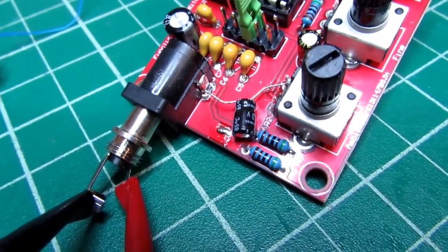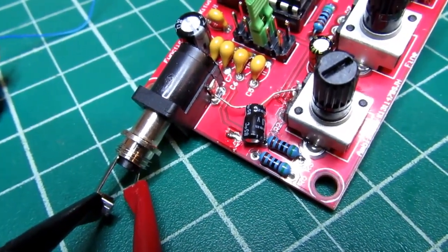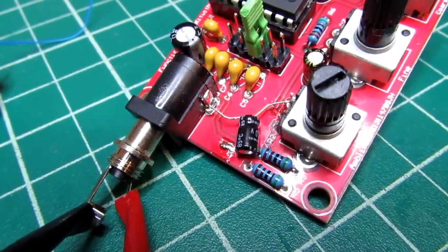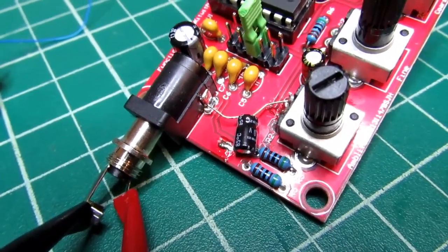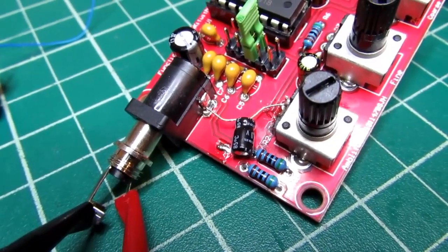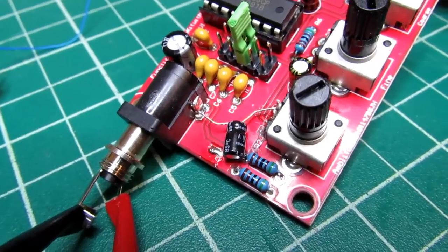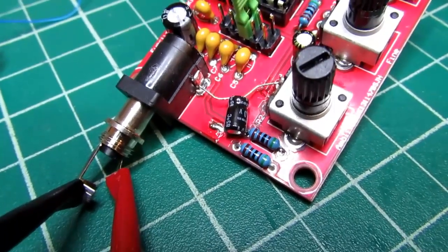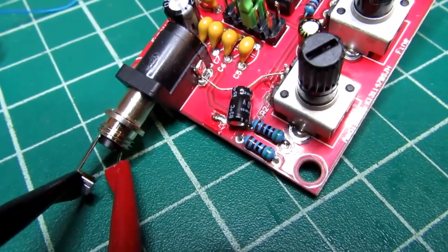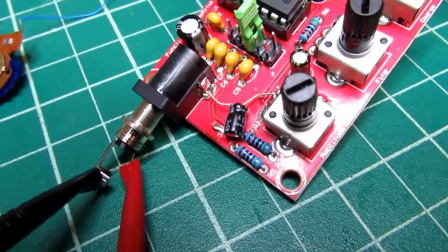I had it incorrectly connected before. I had it connected to the wiper of the amplitude pot, in other words the pin that goes directly into the IC, and that was just because of the weird way the schematic was drawn originally. It needed to be at the center of that voltage divider instead. Now again, that's probably not strictly needed, but since the datasheet unequivocally recommends it, I put it in there, and now it's not messing with the operation as it did before. It's just a matter of getting it connected to the right side of the potentiometer.